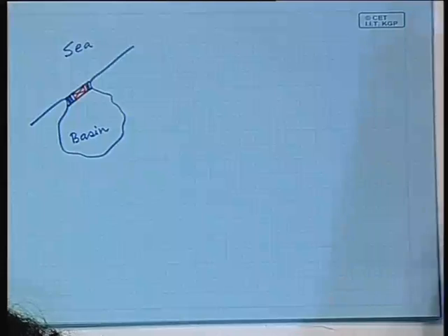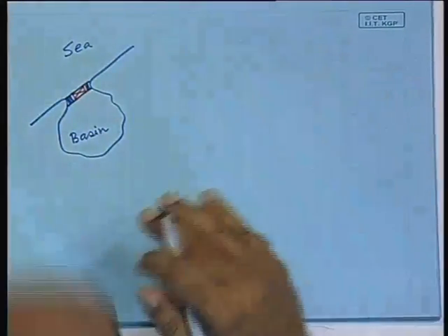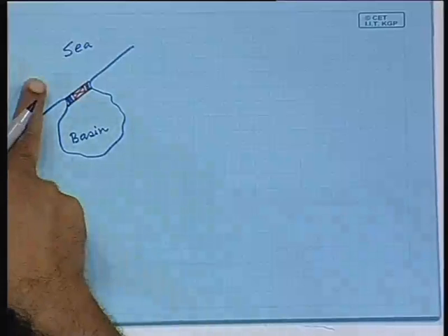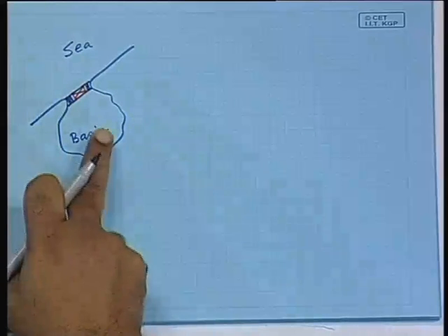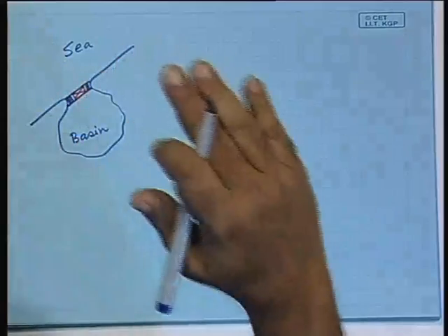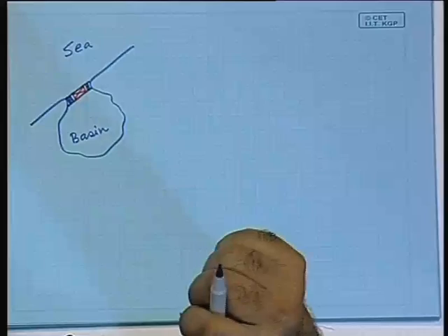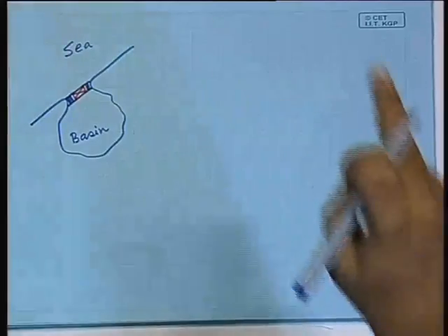Now, let us draw the cycles of the various levels. What are the levels? There are two levels available, the sea level and the basin water level. Sea water level during the tidal variation would vary approximately sinusoidally, and the sinusoid will have a time period of how much? 12 hours 24 minutes. Within that there would be a full sinusoidal cycle of the sea water level.